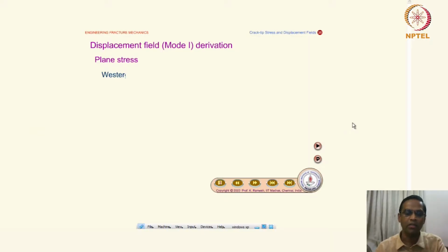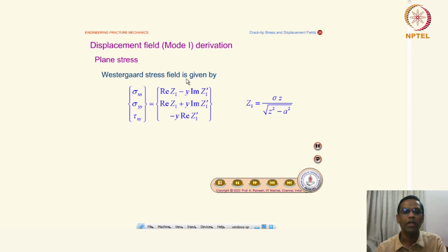In the last class, we looked at the stress field near the crack tip, and I would like to continue in this class to look at the displacement field in the mode 1 derivation. So we'll first look at the plane stress, what is given by the Westergaard stress field. So this is already established.